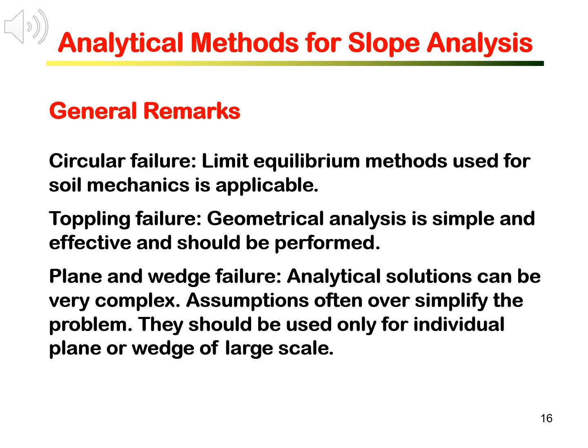Toppling failure happens with block mass with subvertical joint sets. The blocks are generally detached and can topple. Toppling can be analyzed by geometrical analysis, simply by checking block geometry and the tilting angle.